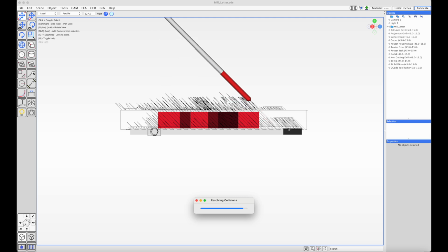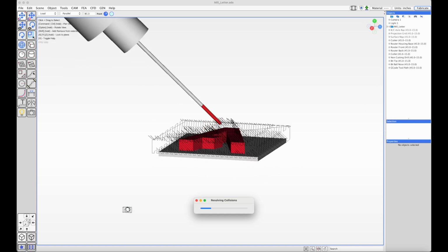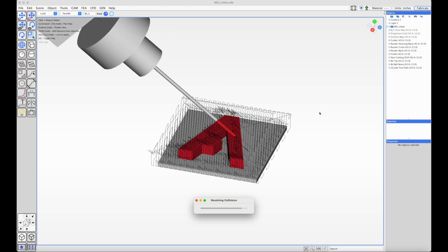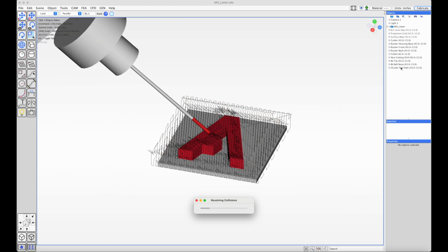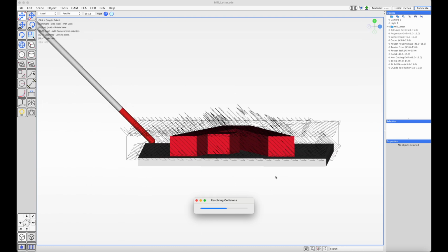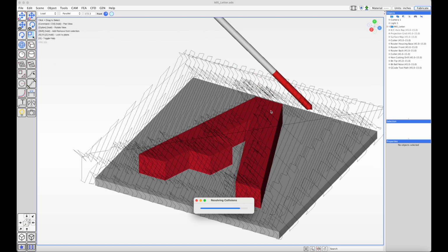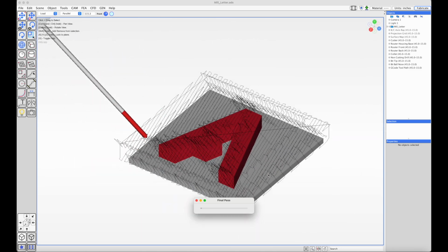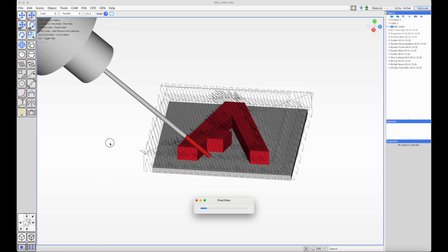So in this case we've got two layers. It does take a long time. I'll just let it finish. Right now it spits out debug information for how it calculates the toolpath, and then this is the geometry of the router that it will use for the collision detection. So we want to cut the surface of the model. We don't want the drill bit to protrude through the part. So the final pass is running through the generated code, and it's just going to do a final check to make sure that there aren't any collisions.